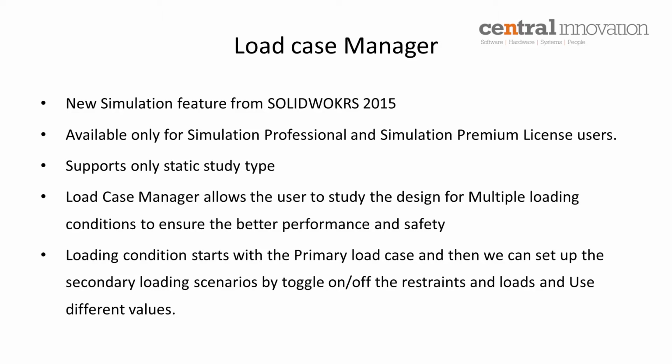How we can start the load case manager is, first, you have to set up a static analysis. That is your initial condition. And then you can create a load case manager and define a primary load case. By using primary load cases, you can create multiple scenarios. Like I said before, you can change the fixture definition, change the load magnitude, suppress the load, change or give equations for the load, and then you can create combinations. You can further linearize and combine the primary load cases by using the secondary combination. I'll show that later.